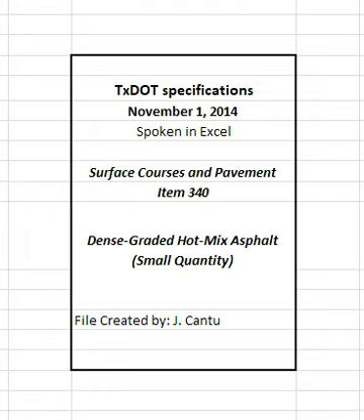The coarse RAP stockpile will contain only material retained by processing over a 3/8 inch or half inch screen unless otherwise approved. The fine RAP stockpile will contain only material passing the 3/8 inch or half inch screen unless otherwise approved. The engineer may allow the contractor to use an alternate to the 3/8 inch or half inch screen to fractionate the RAP. The maximum percentages of fractionated RAP may be comprised of coarse or fine fractionated RAP or the combination of both coarse and fine fractionated RAP.